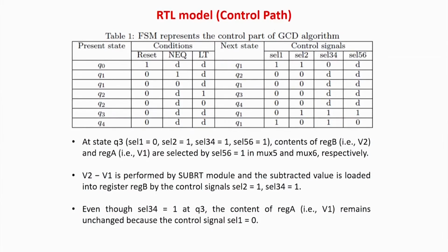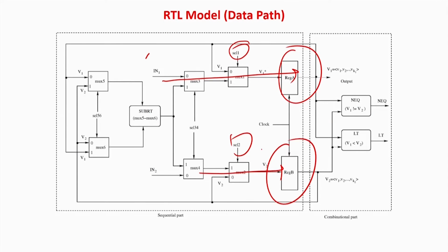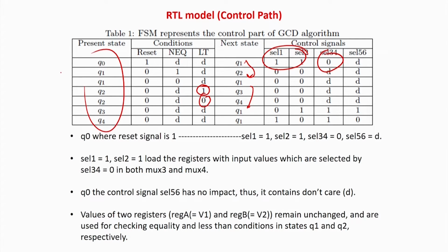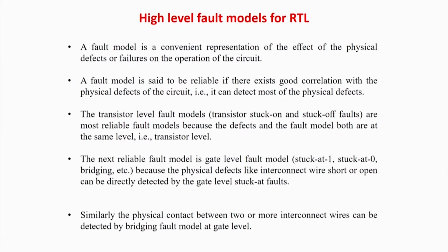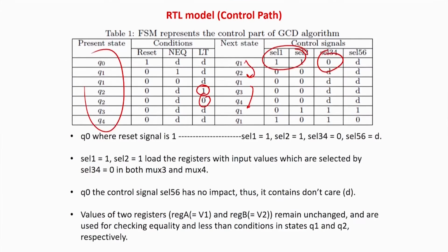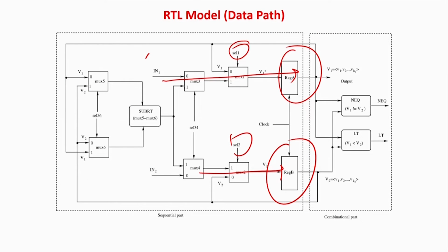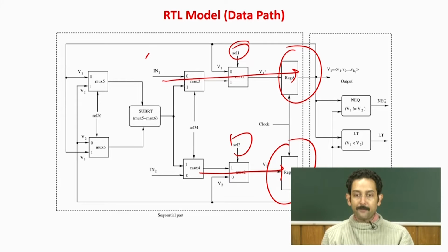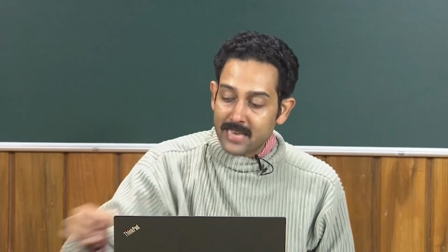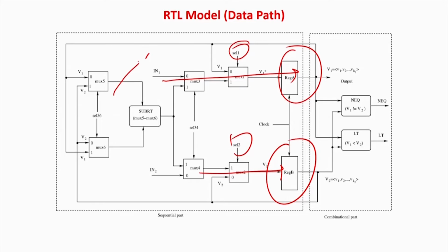And also one more assumption we have, that all these registers, that is the flip flops, and also the flip flops used to represent these states, are scan enabled. That is obviously very easily possible. Now you can very easily appreciate what I will do with the stuck-at fault over here. You can say that I can only have stuck-at faults on the inputs and outputs. You can do that, but people have found out statistically that that is a very devastating fault model. No correlation can be found, not even 20% correlation, if you directly apply a stuck-at fault model over here. It is not that people have not tried. People have found out that the stuck-at fault model is well accepted, but I have a very abstract model. Let us try to put some stuck-at faults in this place and see what happens. That means you are considering this whole line together, the whole V1 together.